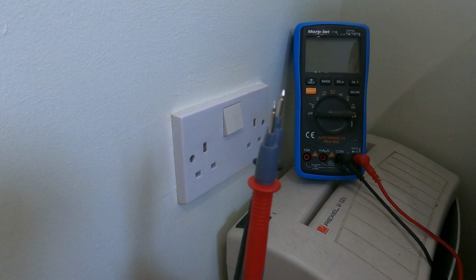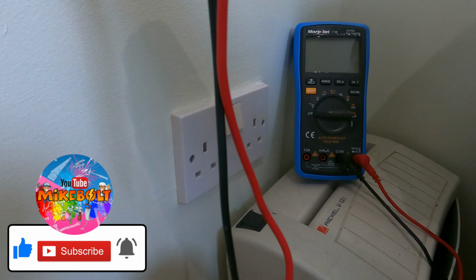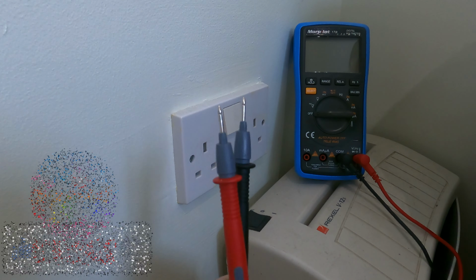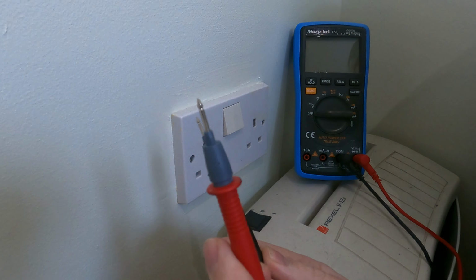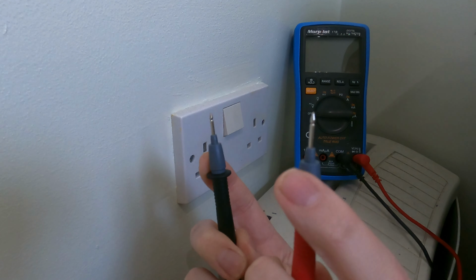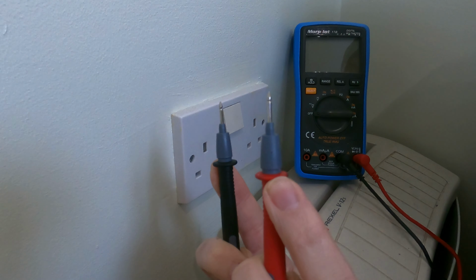So first things first, we're going to do a safety check on our test probes and make sure there's no tears or rips or anything like that anywhere down them. If there is, don't take the measurement, go out and buy some new test leads. It's not worth taking the risk. Secondly, when you're taking the measurement, make sure your fingers are behind the actual guard of the test probes. You don't want them up here, you don't want them anywhere near the metal, so make sure your fingers are well away from the metal.